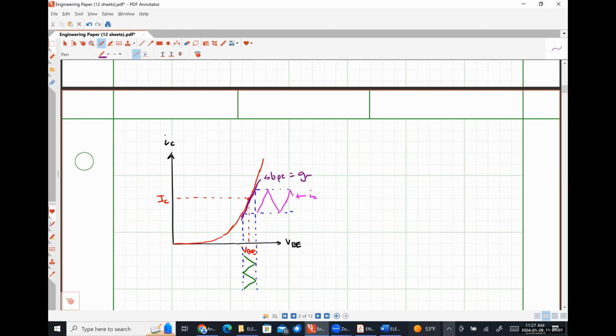Yes. What is the slope on that slope? Literally the word slope. The slope of this purple line is the transconductance. So that is the slope of the tangent line at the DC operating point, right? So if our DC operating point were somewhere down here, our slope would be lower, our transconductance would be lower. Ideally, we want our slope somewhere in this portion of the curve where the slope is very, very high, because that means we have a very high transconductance.